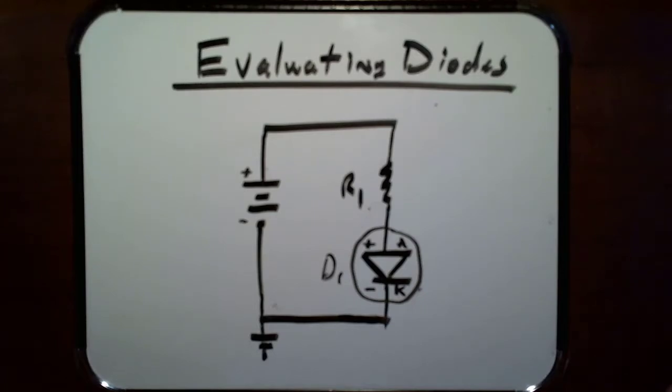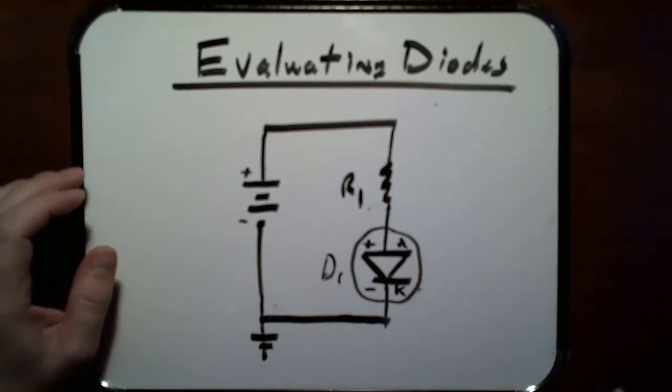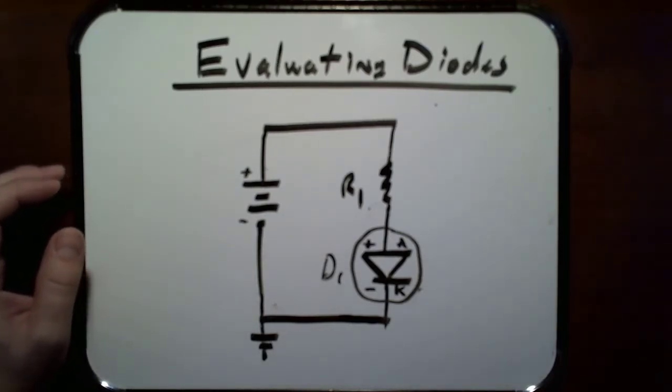The rest goes to our resistor. But first we need to know if it even turns on. If it doesn't turn on, it acts like an open switch. And that open switch has infinite resistance. It won't conduct anything. The electricity can't jump the gap, and so we have possibly an open leg of a circuit, or in certain instances, the whole circuit isn't even turning on. So let's take a look right now at a diode that is conducting, and let's see how it behaves.